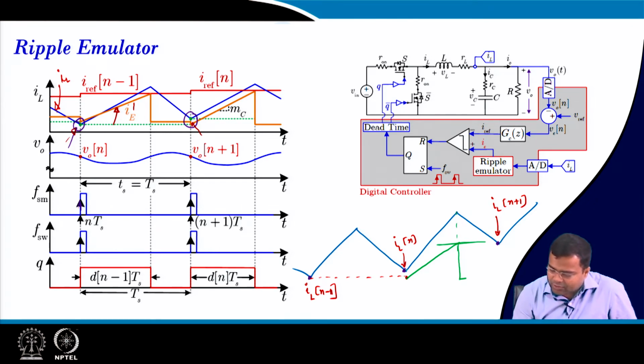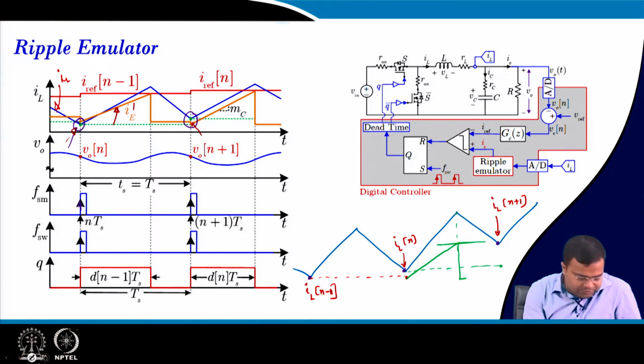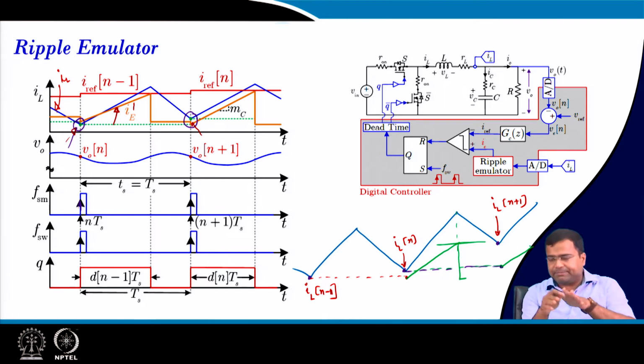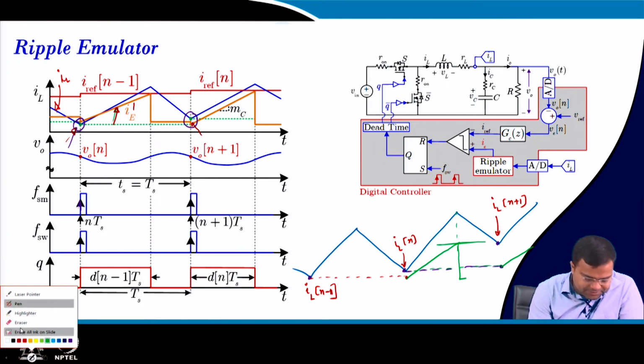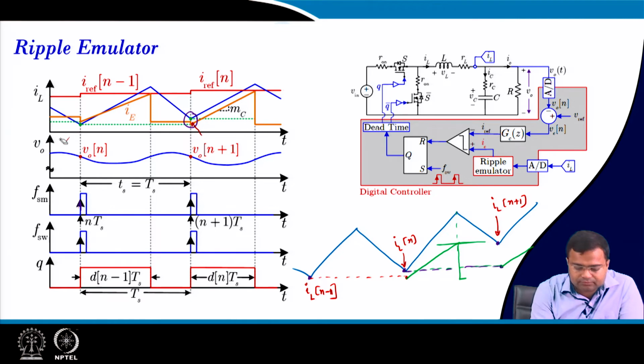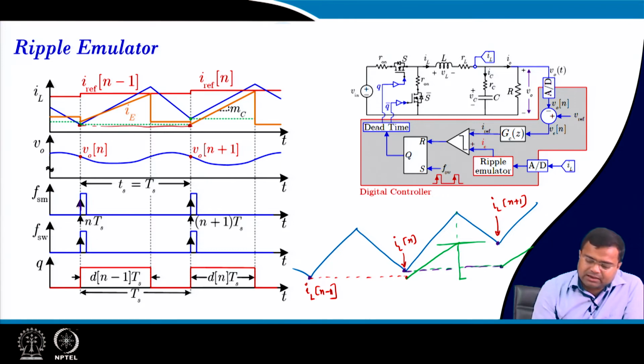Next time, now this sample point is extended. So, this sample point is extended here, that means we are using this sample point, but our sawtooth waveform, our ramp signal, will start from here. Again, it depends upon the peak current. So, that means you can see this waveform, that means if I rub out all this part. So, you can see the sample of the inductor current is used in the next cycle here, and with an added ramp.